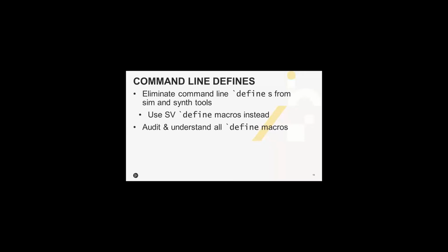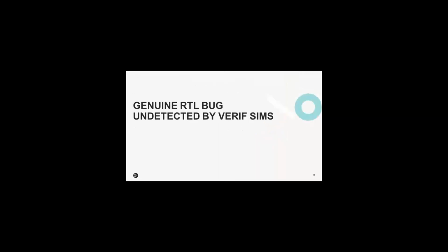Right, final word on defines. Of course, on your command line, you can also issue defines, so you need to make sure that they are the same in your simulation tool and your synthesis tool. I would encourage all those defines to go into SystemVerilog. That's what I would do. And you want to make sure that you really understand what all your defines do.